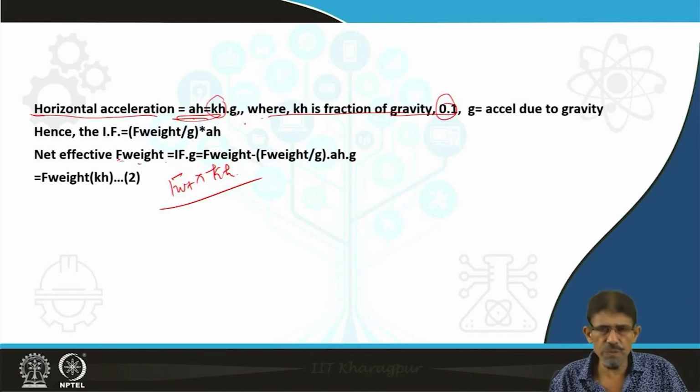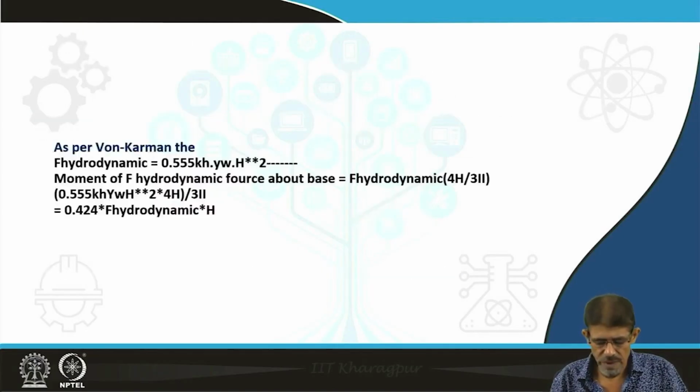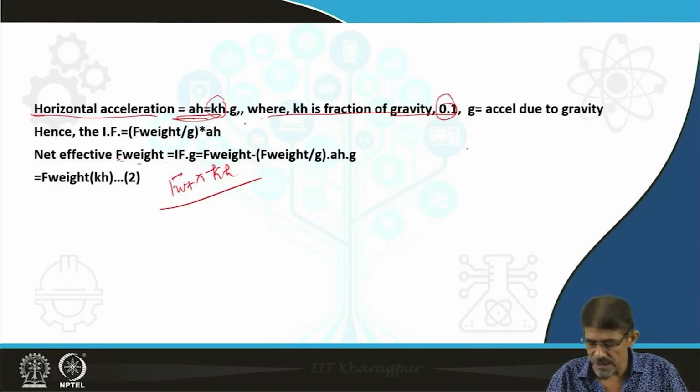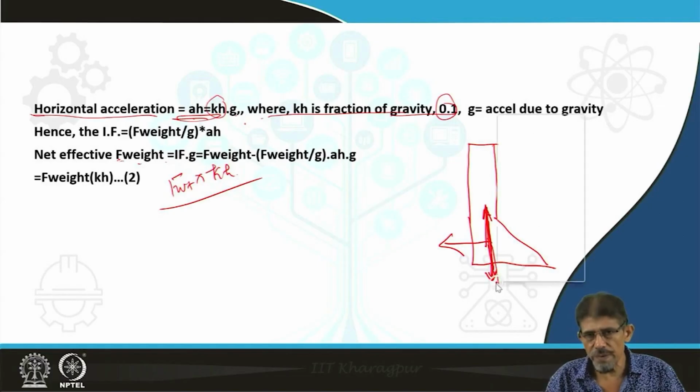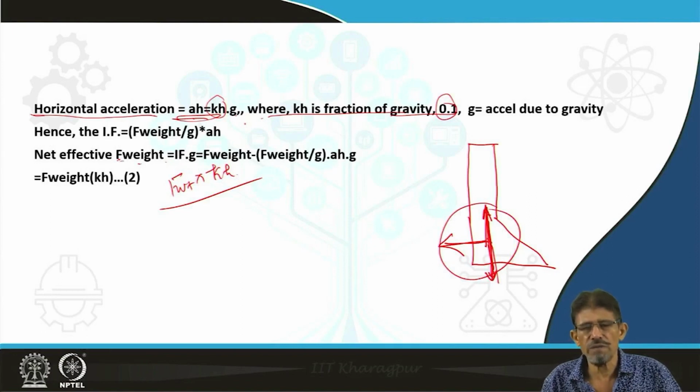Now a question: sometimes people may ask which situation is suitable for movement of the dam in case of horizontal and vertical acceleration. You can see here downward vertical and toward the upstream horizontal. If it is downward, then inertia opposes this and tries to stabilize, and it helps. This upstream side is the best combination from a stability point of view.